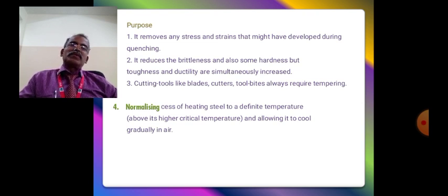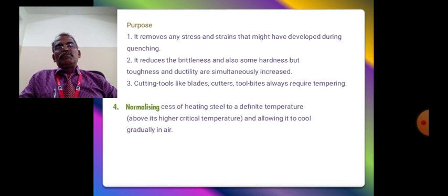And also another important point, it reduces brittleness and hardness, but toughness and ductility are increased. Cutting tools like blades, cutters, and tool bits always require tempering. So cutting tools generally undergo the tempering process.